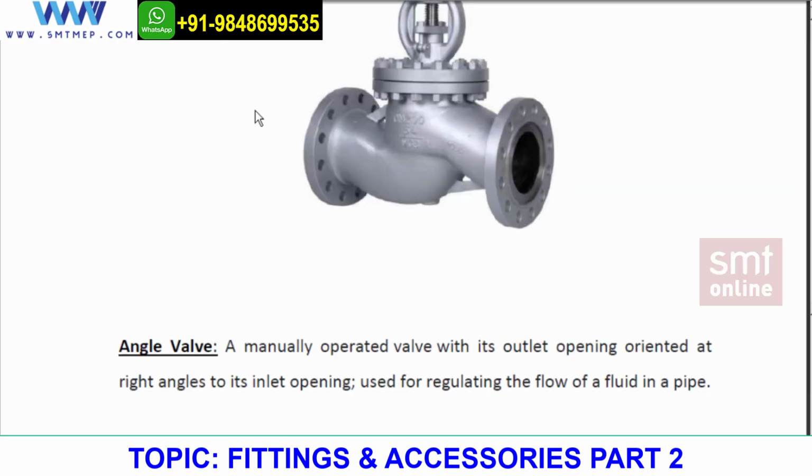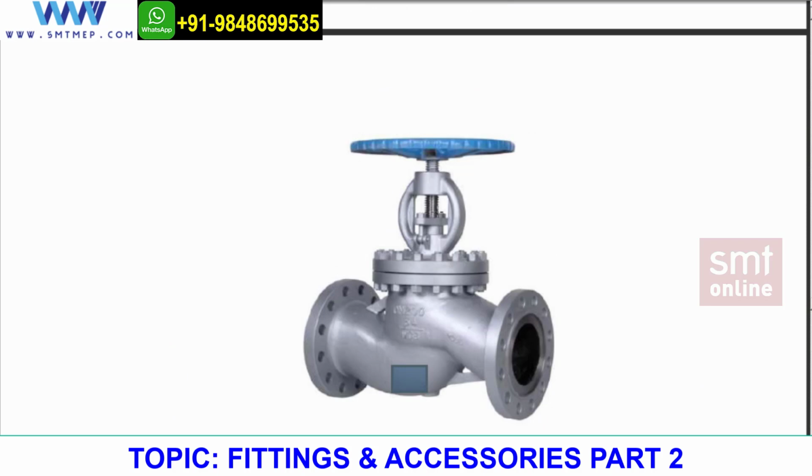The water goes in this manner. The water enters here in this manner. First of all, it stays over here. The moment I rotate this, as you can see, the stem with the cylindrical spherical body will be lifting up and up and up, and the more upper, the fuller. For example, if I've opened completely, for example 10 GPM, I will be getting almost the 10 GPM on the other side.